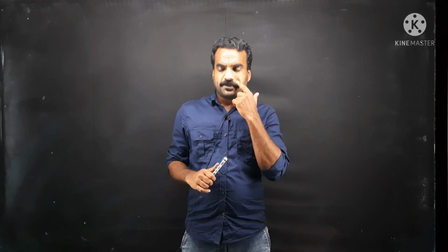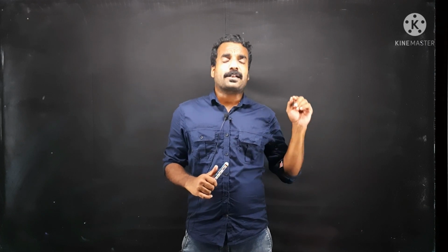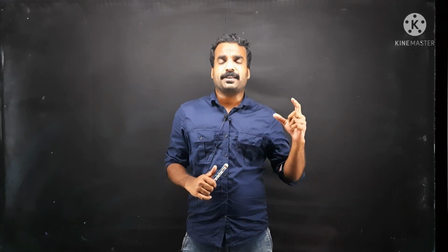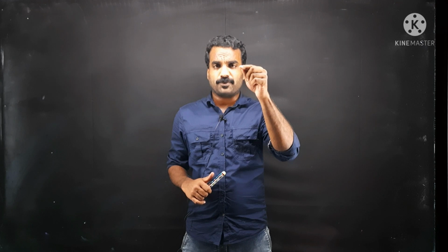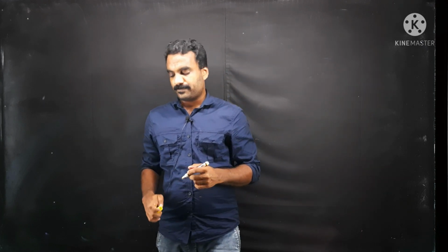The line perpendicular to the resultant flux line is known as the magnetically neutral axis. The direction of main flux is from the origin towards the x-axis, and the armature flux starts from the origin and passes towards the negative y-axis.